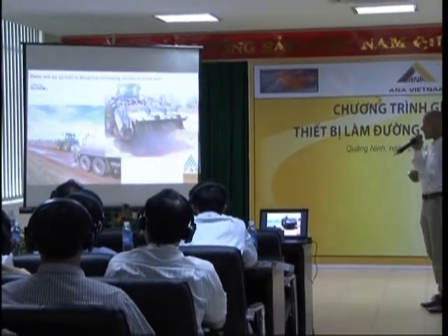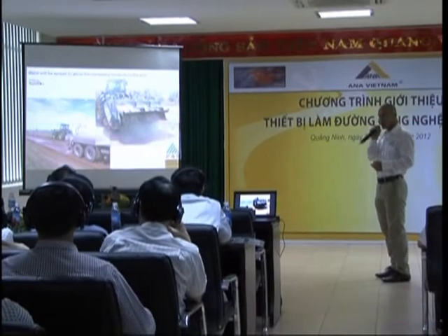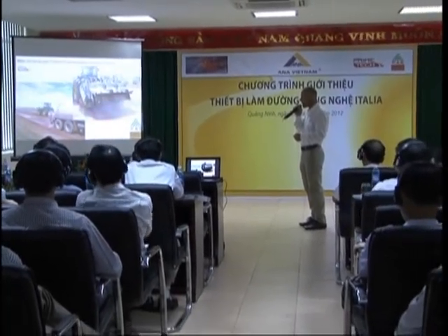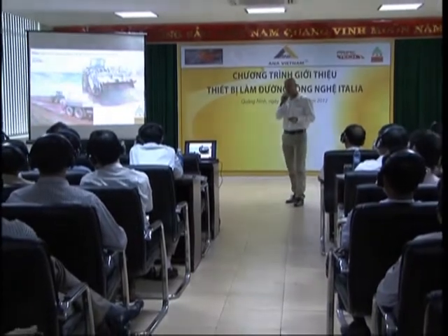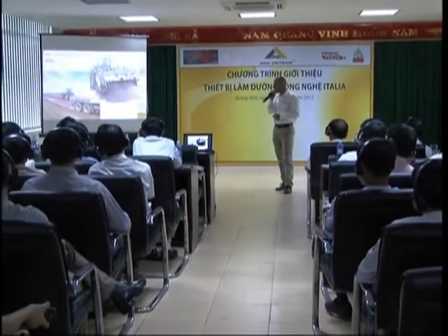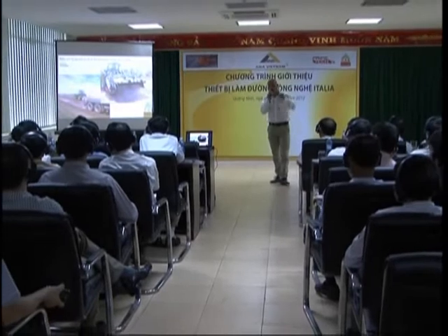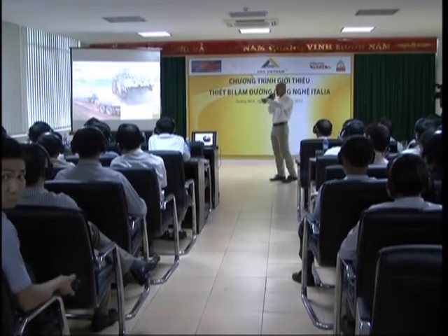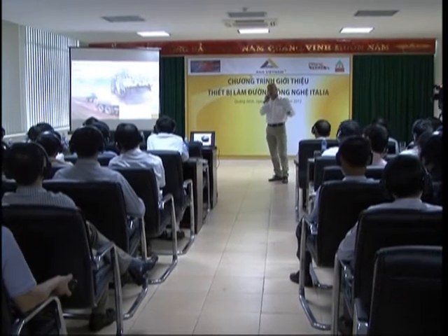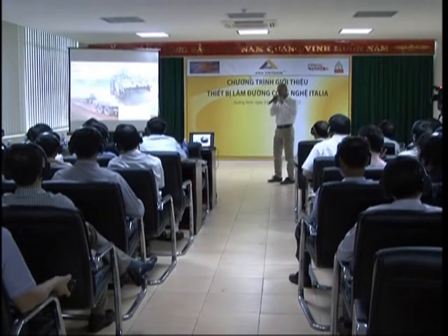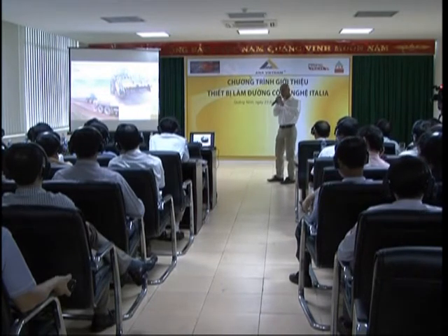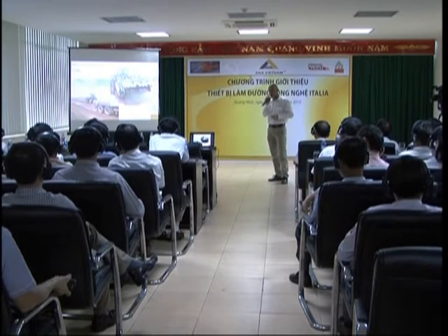You can add water in the machine. Connect the machine to a water truck, and the machine has a pump and everything. You can spray water. But in the mining operation, you already have this truck, so it should be easy for you to add water if necessary. Because if it's very wet like now, you don't need water. But in summer, maybe you need water, because you need to have what they call optimum moisture content in the road when you mix together with cement.